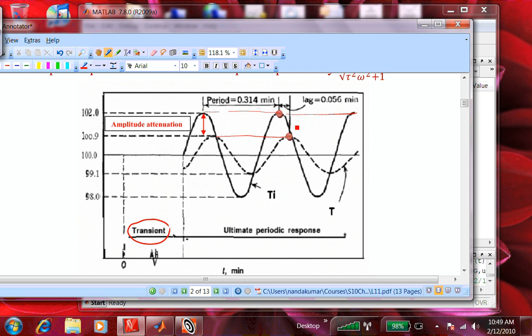This is still the thermometer problem. Now you might ask, how am I going to force a sinusoidal change on a thermometer? Can you think of an example? Remember, we started this model by dipping a thermometer into a vessel and developing a first order transfer function. So all you need to do is expand your time horizon, and you can see a lot of situations in nature where the oscillation is periodic.